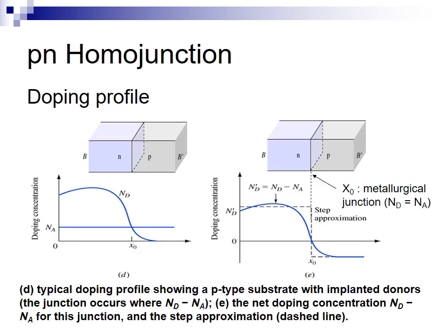Looking at the doping profile, the actual doping profile is shown in figure D. Since we are using a p-type silicon substrate, Na is constant. At the region where we doped with n-type doping, Nd is higher than Na. Thus, this region is a compensated semiconductor. The effective doping concentration is then N'D equal to Nd minus Na, as we have learned in chapter 2. At the region with the p-type doping, the concentration is equal to Na.